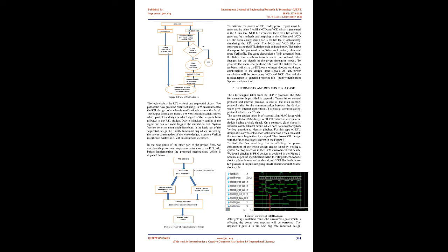In the next phase, the other part of the project flow, we calculate the power consumption or estimation of the RTL code before implementing the proposed methodology, which is depicted below. To estimate the power of RTL code, a power report must be generated by using files like NCD and VCD, which are generated in the Xilinx tool.